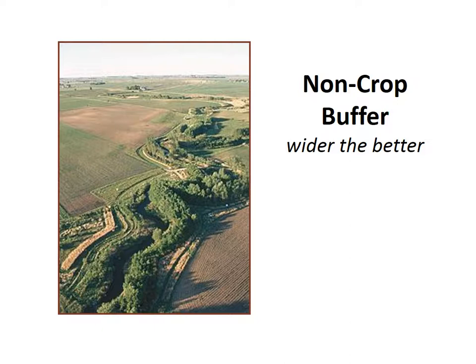Another consideration is to leave a significant buffer along the edge of a high bank. These high banks are often unstable, especially on the outer side of bends. Leaving a buffer of natural vegetation equal to 3 to 5 times the height of the vertical bank will help to accommodate the development of vegetation as the bank erodes.